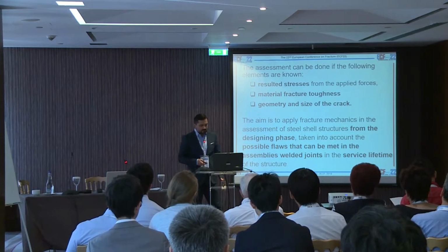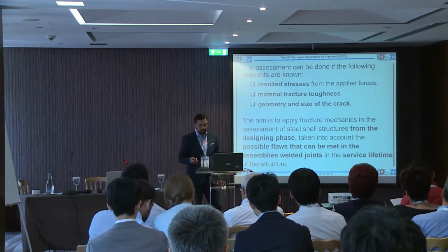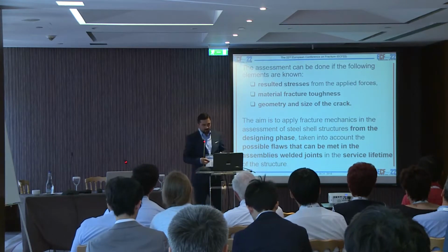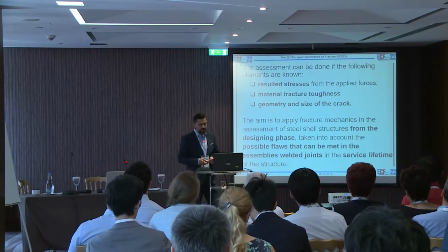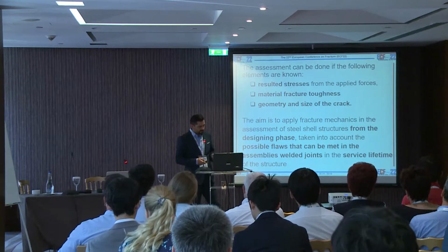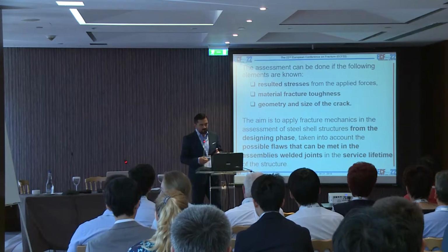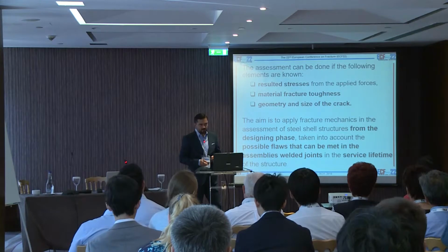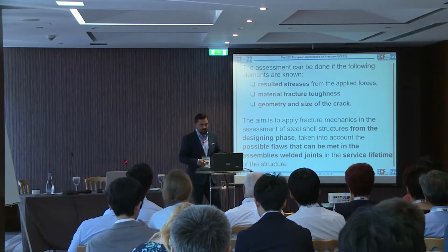Of course, the assessment can be done if the resultant stress, the material fracture toughness, the geometry, and the crack size are known. The purpose of the research is to apply fracture mechanics in the assessment of steel shell structure elements, from the designing phase, as I said before, and to determine if a possible flaw in the lifetime of the structure can be dangerous to the service of the structure, and of course whether repair will be needed or not.